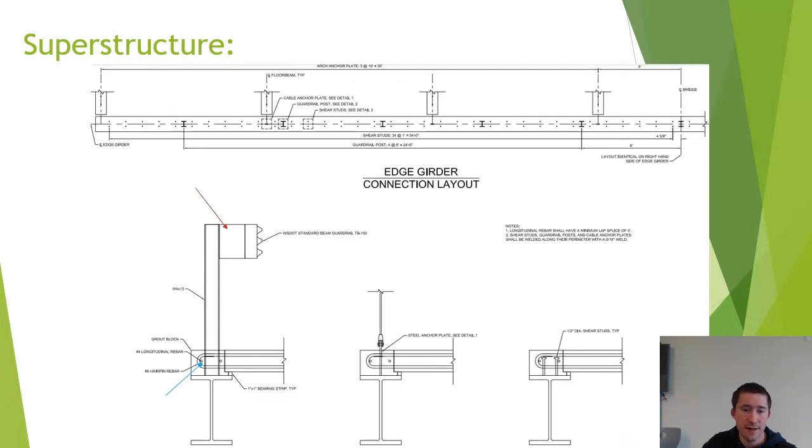This shows the layout of connections to the edge girder, which at present are the guardrails, cable connections to the arches, and the shear studs. All of them will be welded to the top of the girder. Whether this will be okay structurally for the guardrail and anchors is yet to be checked.